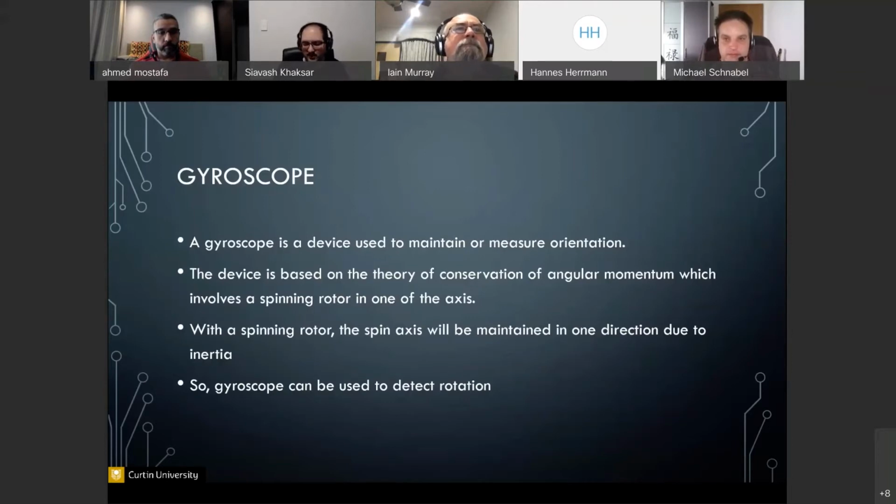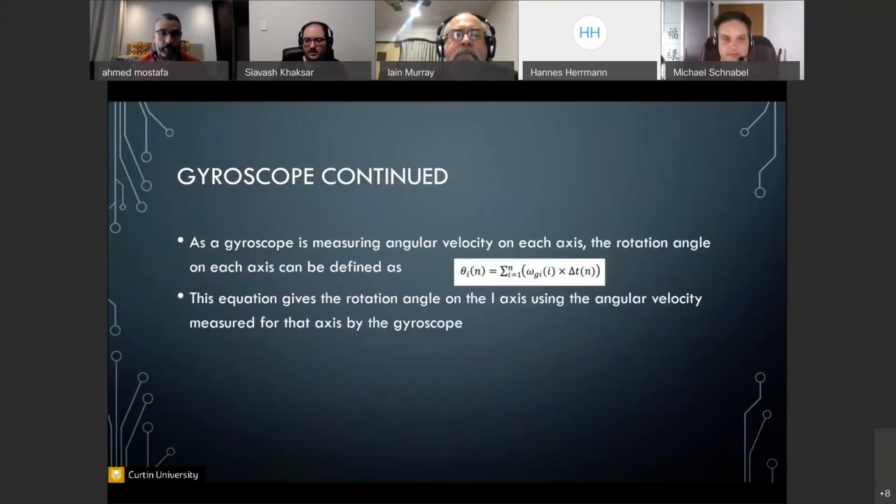If you're interested in using IMUs, because I have a lot of experience with them, send us an email through that IoT capstone. I have a handy file, I've called it the IMU links file, and I can send those links to you, so that can help you get started in getting data, converting that data to movement, acceleration, angular velocity, and then finally processing using the accelerometer and the gyroscope to get an orientation frame through MATLAB. If that's something that interests you, let me know. Here are just examples of equations we can use with the gyroscope to measure angular velocity.